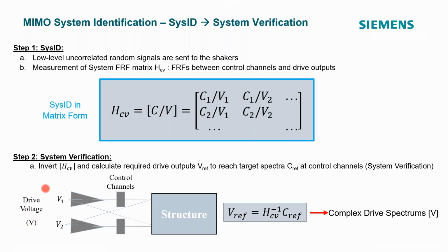So we're going to do that verification where we extrapolate up, know our full level responses using our low level transfer functions, and we're going to predict what we're going to see at full level. So that's our so-called self-check for multi-axis control. We call it system verification. I don't know why we changed the name, but that's the way it is.